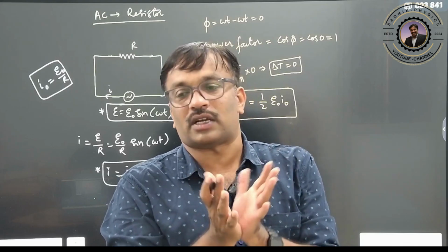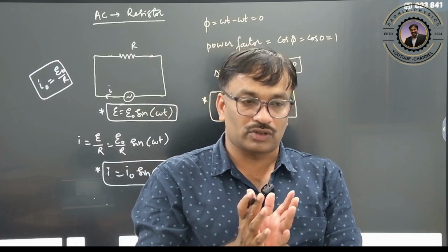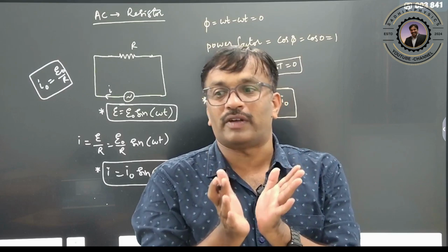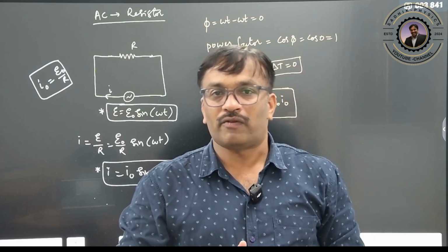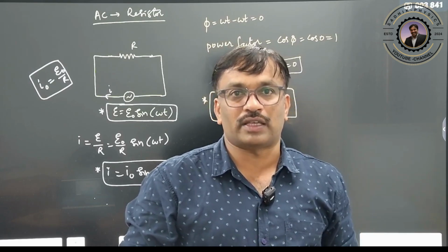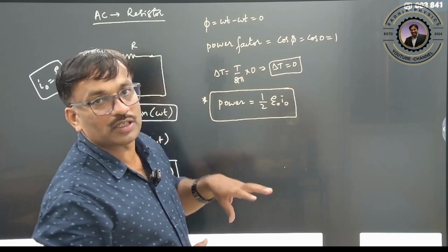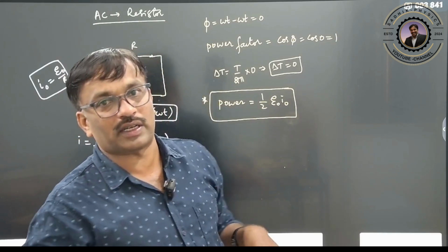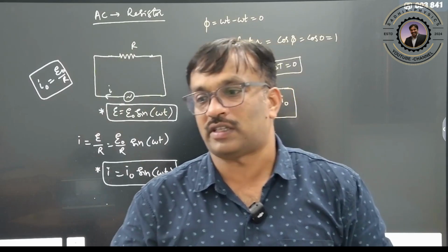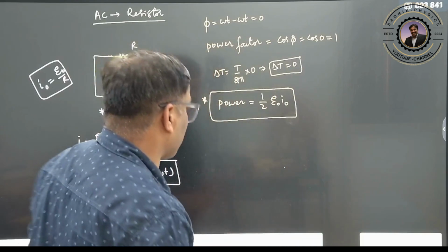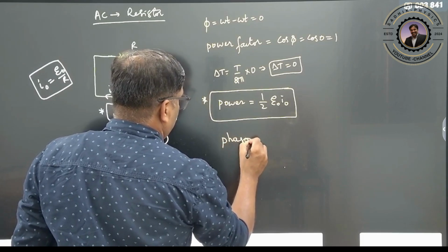These two vectors, a current vector and a voltage vector, are represented. The angle between the current vector and the voltage vector is nothing but the phase difference. Whenever you are dealing with waves like this, you have to take the phase into account. Therefore you can solve these concepts using phase vectors, simply by using the parallelogram law of addition of vectors. So we can write it as phasor vectors, the phasor diagram. This is an important one, the phasor diagram.